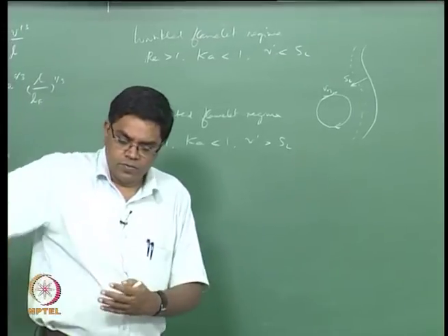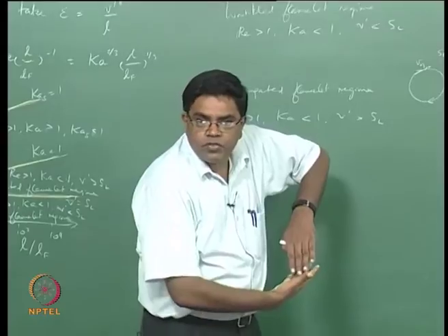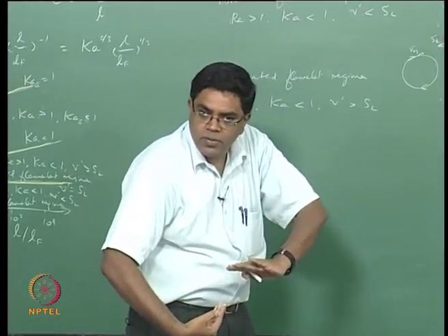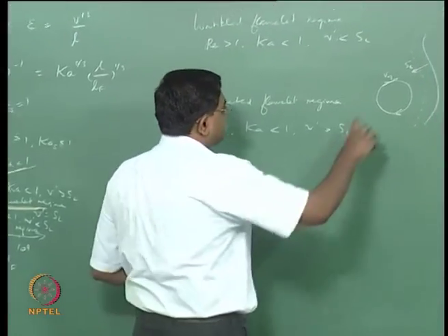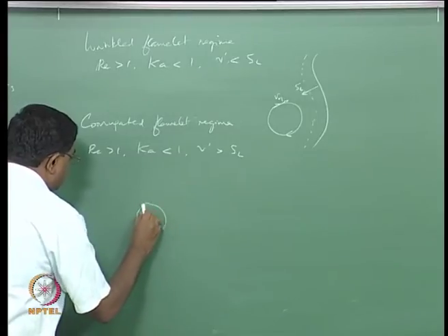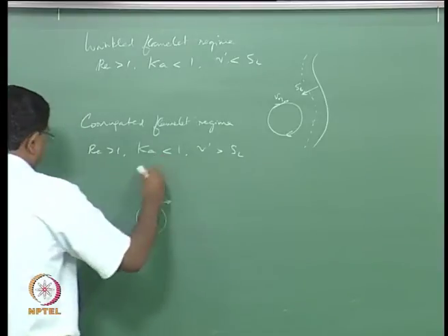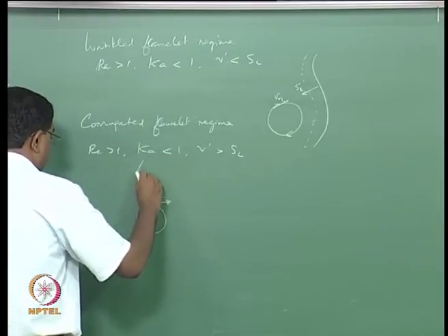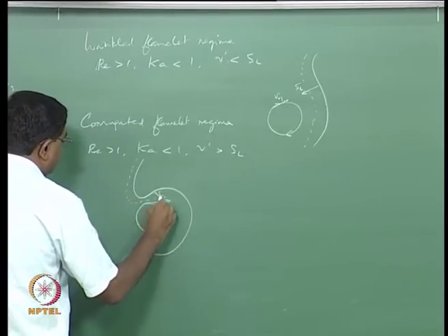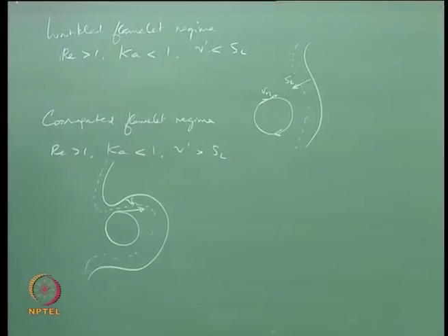When the flow is locally large, the flame gives way by inclining itself to the flow such that only a component of the flow direction is balanced by the flame speed. So what happens when this begins to increase is, if you think about an eddy that now has a larger Vn, and a flame interacting with it, the flame begins to curl up to encompass it.